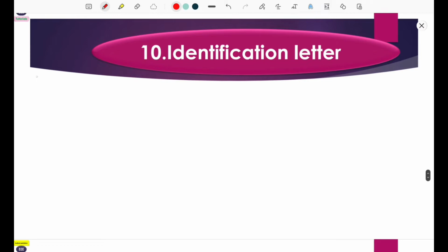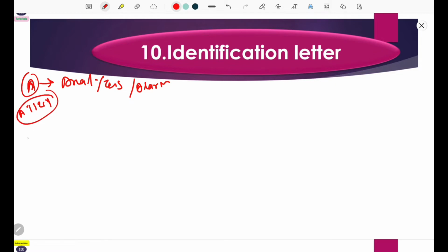If the letter A is written in your P&ID, the simple meaning is analyzer or analytic instruments, or it may be alarm identification. For example, AT 801201 means this is an analyzer, or ALL means it is a low alarm value.